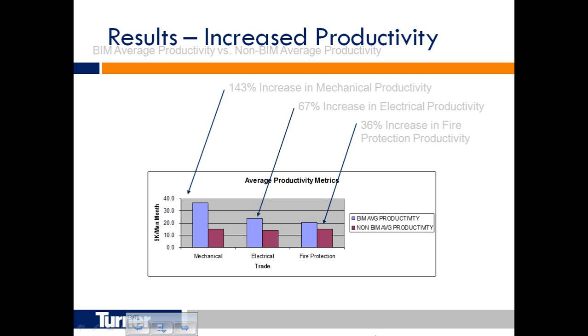And one of the things we start to look at is how many passes do you have on construction. What I like to call it is single pass construction. For sprinkler installers, for example, we're in hard lids. We're able to have them come in, know exactly where their heads are going to be, and have them set them to an elevation rather than measuring off the floor.